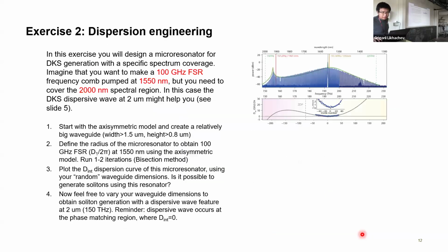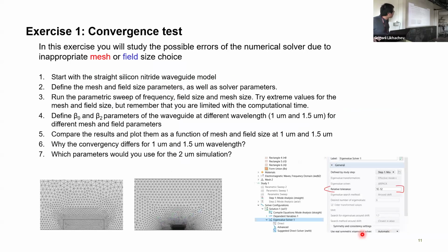These are things that you can try out yourself, based on the sample model that I sent you guys. First, try out how fine the mesh needs to be to get a reasonable dispersion parameter and also a reasonable effective index.